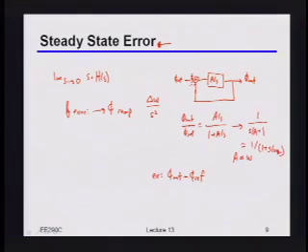Because if it's a first order loop, all I really have to say is what the bandwidth of that loop is. I know that the gain at DC is infinite, so there should be no DC error. So that's all I have left to talk about, right?